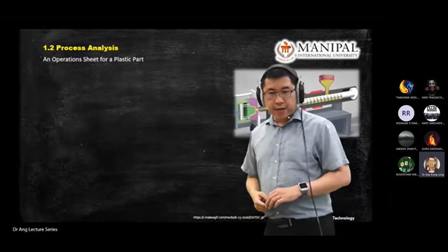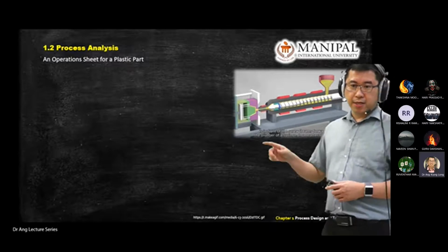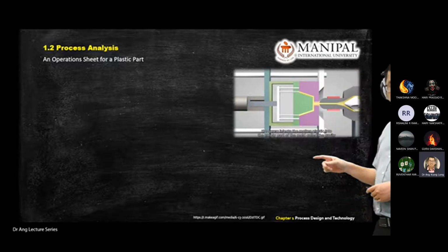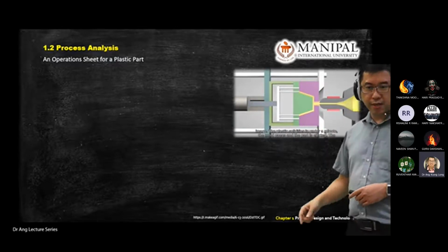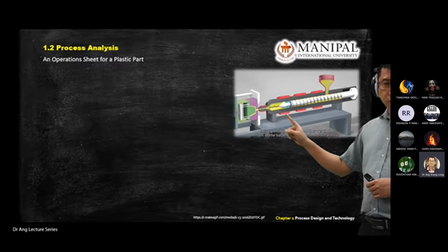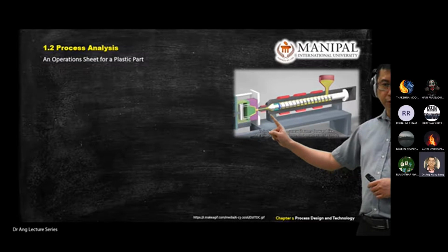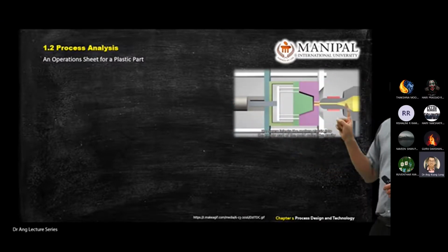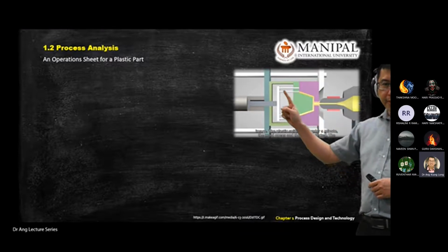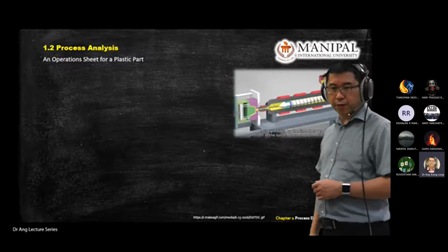All right. Now I'll give you another example. Let's say you want to manufacture a plastic part. Okay. So I think some of you haven't seen how people make plastic part, right? So you have one short cartoon here. So what it does is that the plastic will squeeze and melt in this region. Okay, then you will force pump the molten plastic into the mold, injection mold here. So inject inside, the molten plastic will go into the hole here, and then a release of the component.